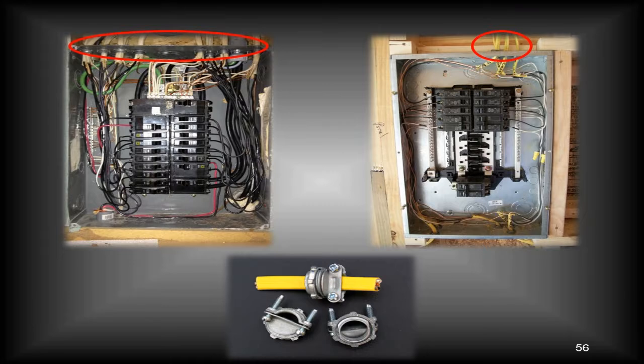frowned on? Well, code says that you're only supposed to have one wiring method per connector type unless it's listed for something different. You know, if you can have multiple wires and it's indicated on a UL listing or something like that, that's fine. Okay, but these aren't.